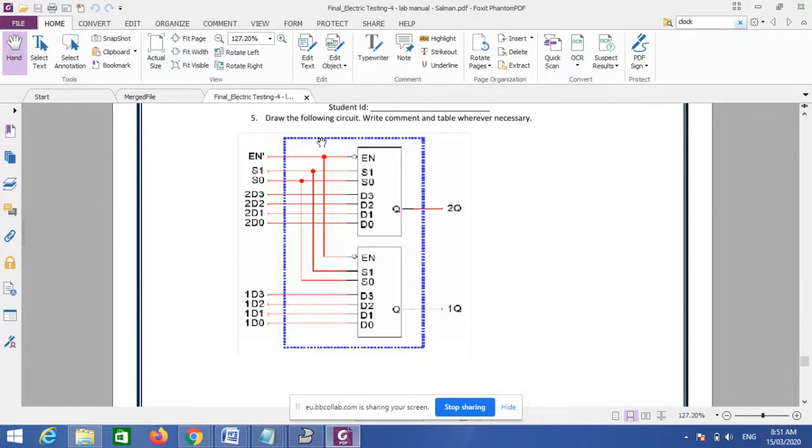So you have to convert this textbook notation into your multimedia logic simulator. How do you do that? For that, let us understand. Now, what is this? This is a multiplexer. Yes, this is also a multiplexer. Which multiplexer is it? Now you see here, it is taking 4 data lines, so it is a 4 to 1 mux. It has one enable and 2 select lines.